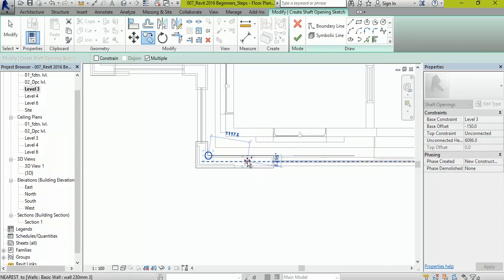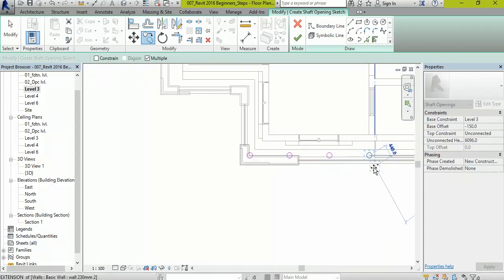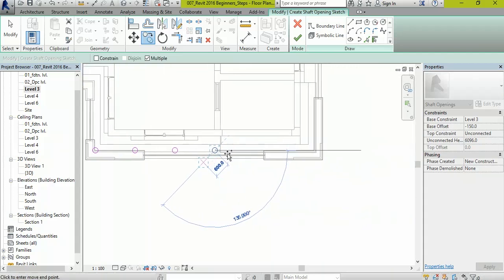So now you can type 1500. That's the distance I want them to be. The distance between each hole should be 1500. Go ahead there, 1500. We can, let's see, let's put one again, 1500.